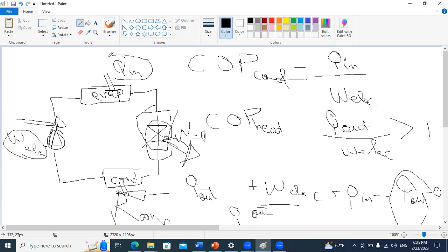Very good. For example, you know that the majority of power plants that generate electricity work on this system because you can use the fuel to do combustion. Let's say the combustion will produce heat. The heat will be given to your fluid at the evaporator level, and then when you take the fluid through the turbine, during the expansion you have production of work in your turbine.